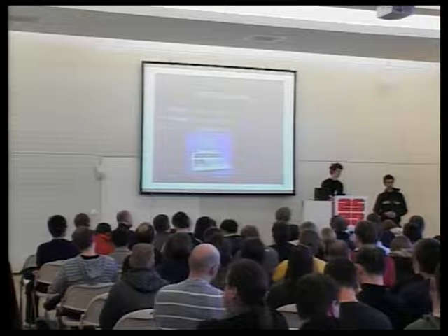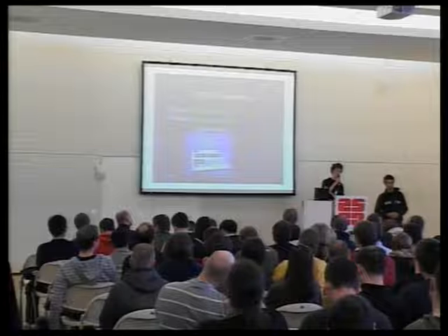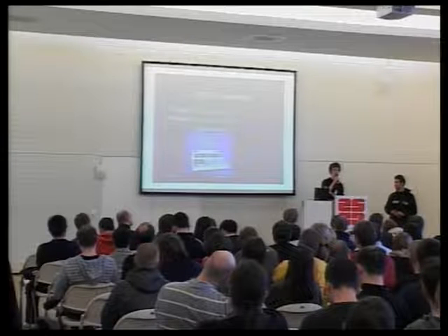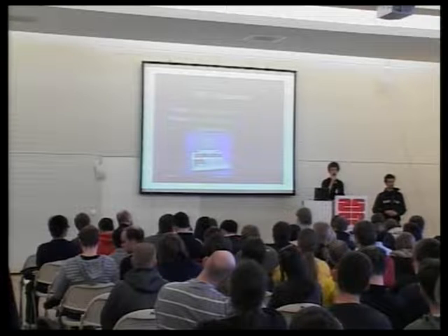IEEE is now also doing a draft for outdoor implementation called IEEE BPL. It's very, very similar to the DSL architecture, in fact. Your physical layer is almost the same because your copper and cables are very similar, but you also have work on provisioning systems and things like that. At home you would have, for instance, that kind of router. You put it on the public side, on the emitter, and you get Wi-Fi or HomePlug AV on the home side. It's supposed to be closed.